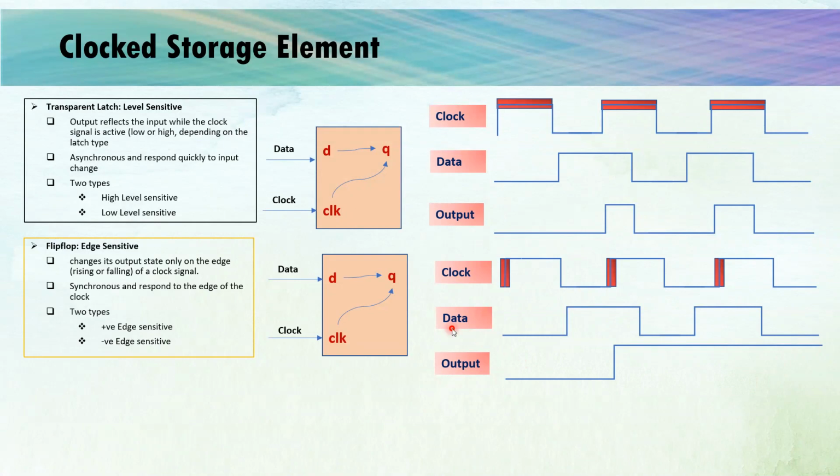So if I talk about some common types of flip-flop, they're basically D flip-flop, JK flip-flop, SR flip-flop, T flip-flop, and many more. So flip-flops are basically used when very precise timing is required, or when synchronization is required within the sequential logic. Like I can give you some examples, like register, counter, or some memory element.